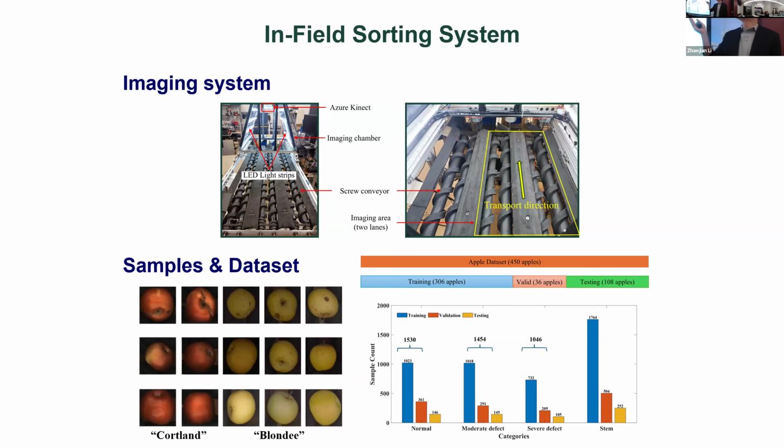So the growers talk to us saying, because you guys are picking the fruits using robots anyways, can you do in-field sorting? We call this in-field sorting. The idea is that after we pick the fruits in the field, we can directly run a sorting line to classify the fruits that can go to fresh market and the fruits that cannot. We do it based on the size, because the size needs to be appropriate. And we look at the color distribution, because some of the fruits in the front, you see that the color is pretty good, but once you pick those fruits and see the back, the color distribution is not very good. So it cannot go to fresh market. You cannot produce high value. And also whether there are any marks, any damages, then it cannot go to fresh market.